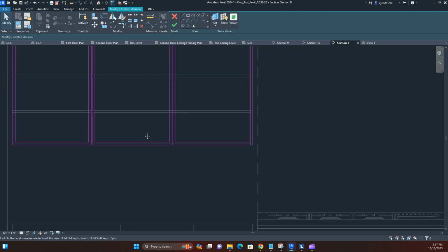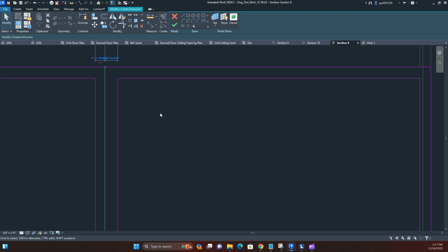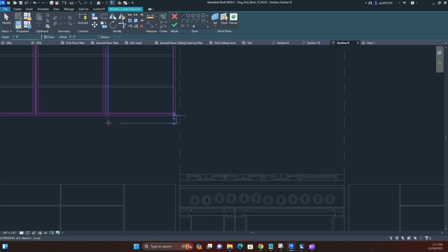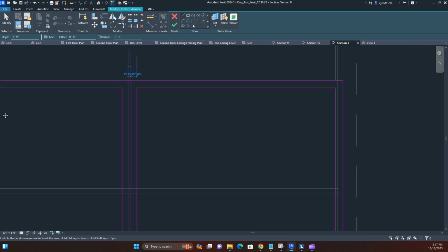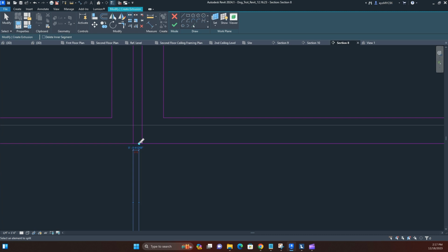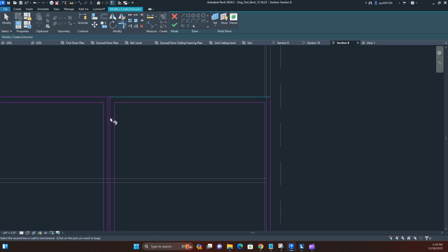So the line in the middle needs to be double for it to be opening. So I need to nudge it a little bit to the left. Then I draw another line. Then I need to split it to give me the opening iron frame for the doors. Trim and extend. Go to the top. Repeat the same process. Trim and extend. Finish it off.